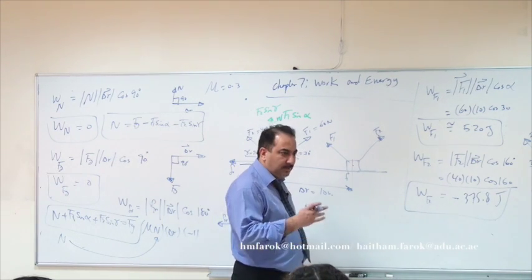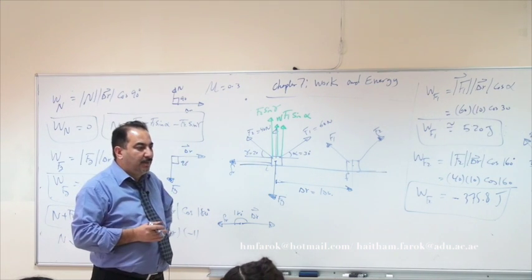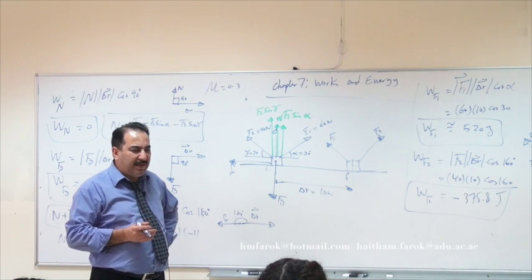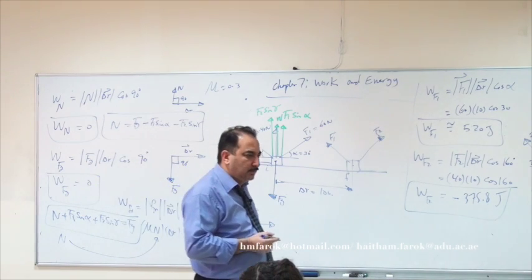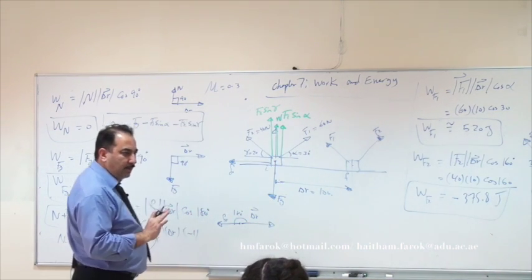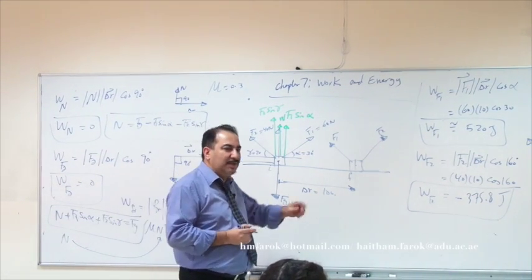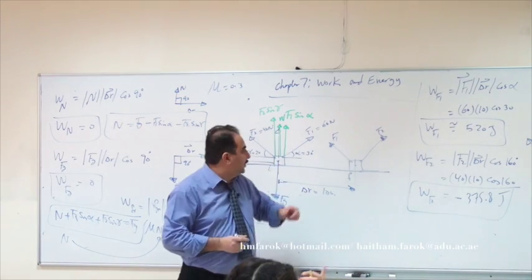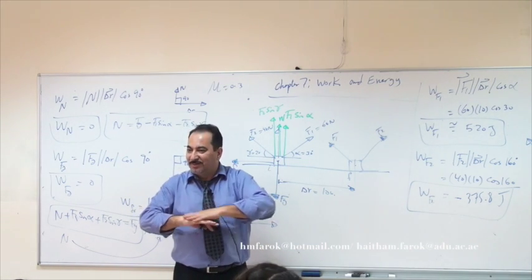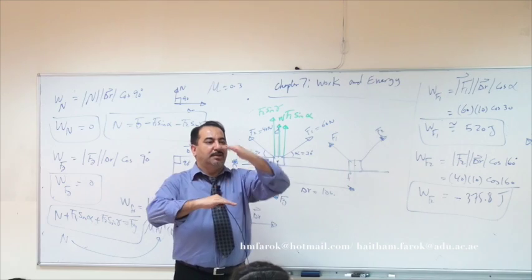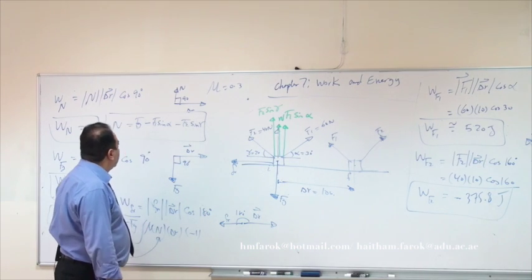You can, no problem, change the mass. Make it so heavy. Good point. So change the mass in the question to something heavy, yeah? It was a 3, yes? Make it 20 kilo. That gives 152.5. So now it's okay, not minus, it's plus. So change the mass in the question to 20. Because I didn't check the values, sometimes the values of these forces are much higher, then you have no friction, and you are lifting the object. Anyway.